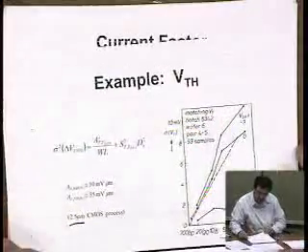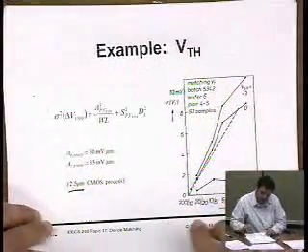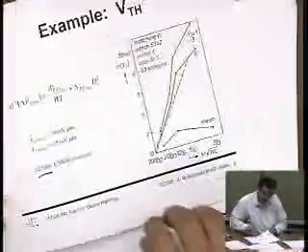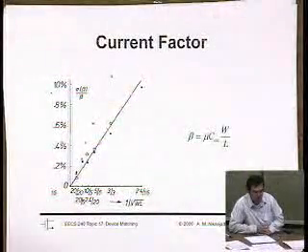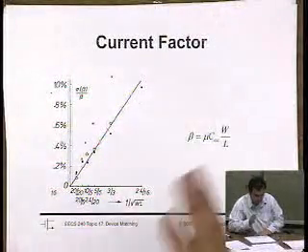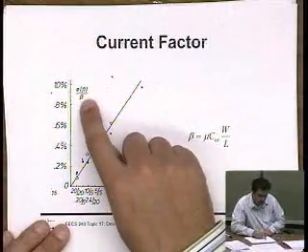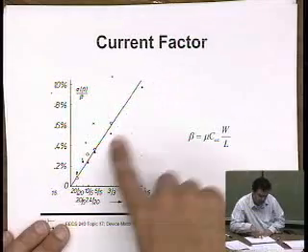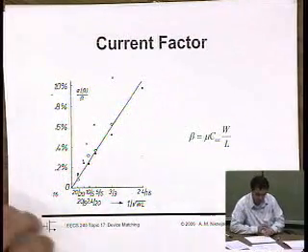The VT mismatch is on the order of 10 millivolts down to millivolts. So in this process, you probably had a threshold voltage around a volt or so. It's hard to tell because this one's normalized. But here you can see that relative beta mismatch is anywhere from 1% down to negligible if you make the device large enough.